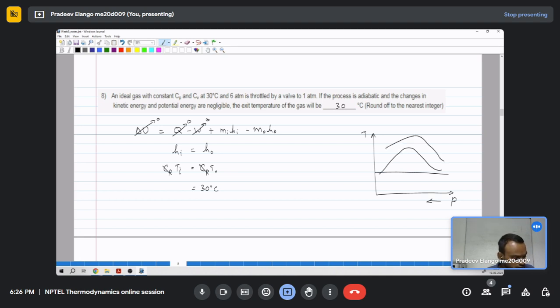And this will occur at different enthalpies, enthalpy H1, H2, and you can join this line, and this is called Joule-Thomson effect. And in case of refrigeration, this portion where the temperature decreases when pressure is decreased, that region is used in the refrigeration cycles. And otherwise this will lead to increase in entropy, which reduces the available work and so on.